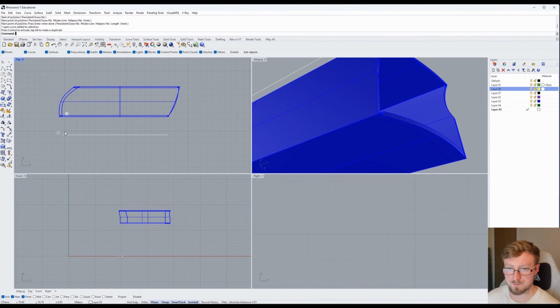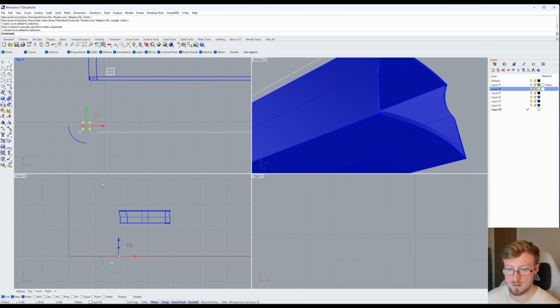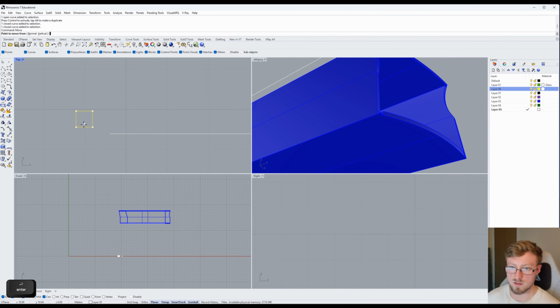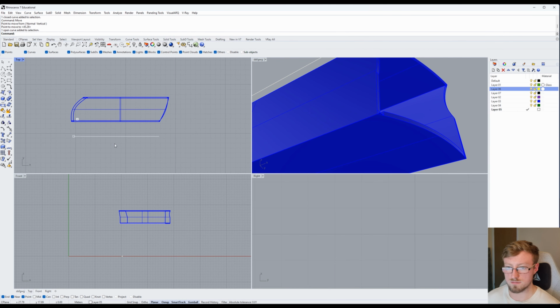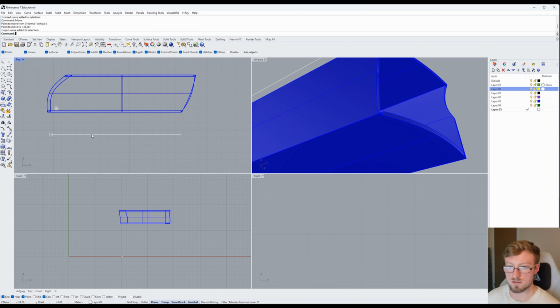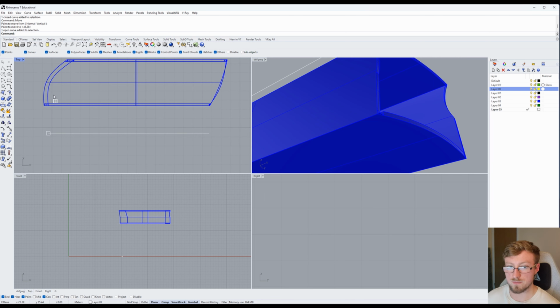Go here. And the center. And move this from the center there. Let's say I want 10 of these spaced out the length of this. What I can do is go to, not a line, array along curve, so that the